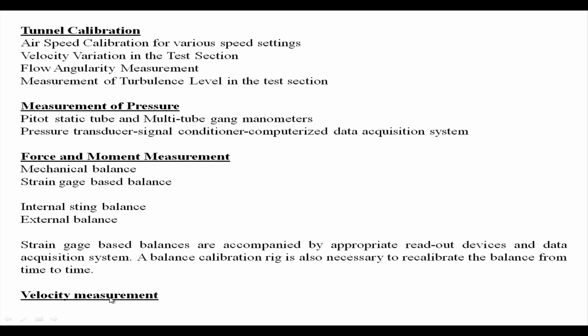Velocity measurement, again a very important issue. So, you could have different methods. You may be looking at a single point measurement technique, something like, say, a hot wire anemometer, but a technique like particle image velocimetry may give you information about a bigger region, not specific to a point. So, again you need to understand your needs and choose what you should be using for that situation,